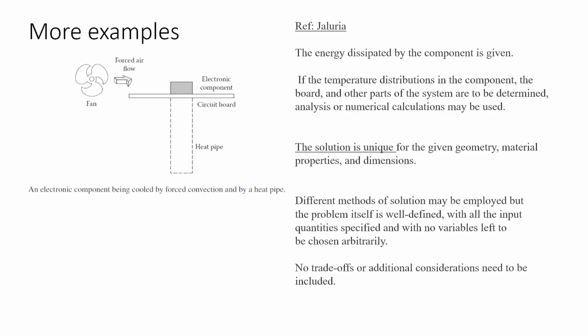Why? Because if the electronic component gets overheated, it will not perform properly. It might fail also. So a couple of things are important. It can get overheated, or even if it doesn't get overheated, if its temperature rises quickly for some small duration, that is also not desirable. So you want to cool it. Now there are various cooling strategies. For example, a desktop computer has a fan which will cool it. There are other cooling strategies also, which we will come to a little later.